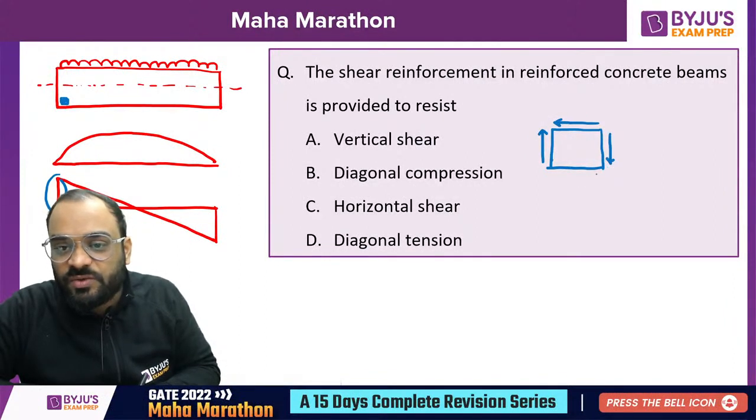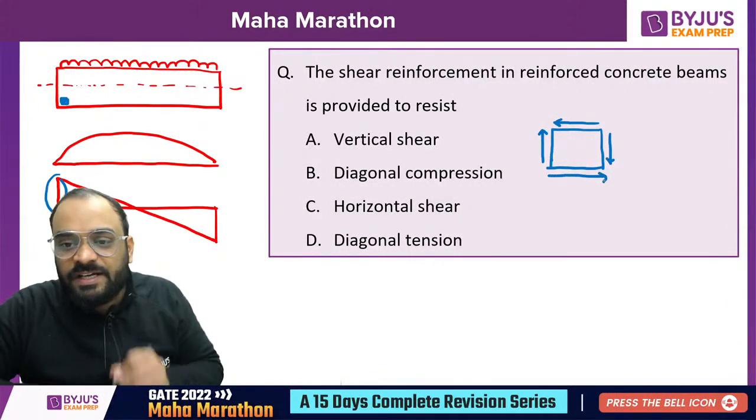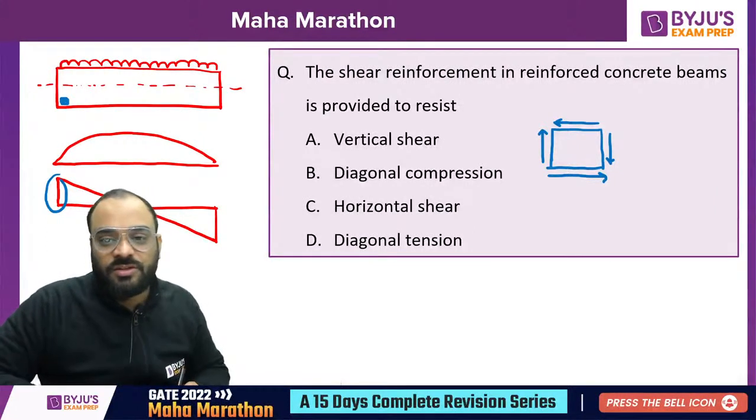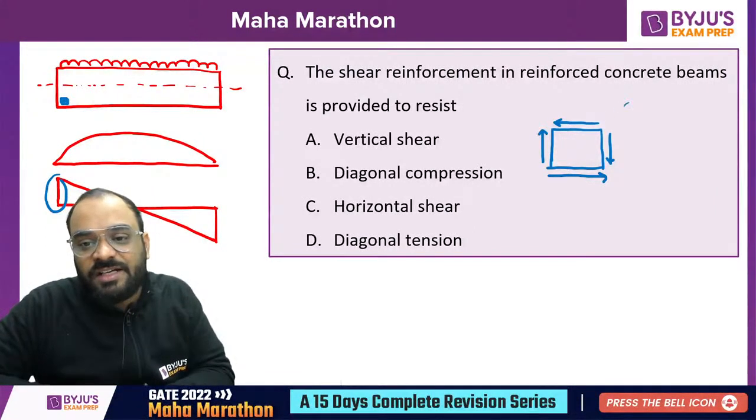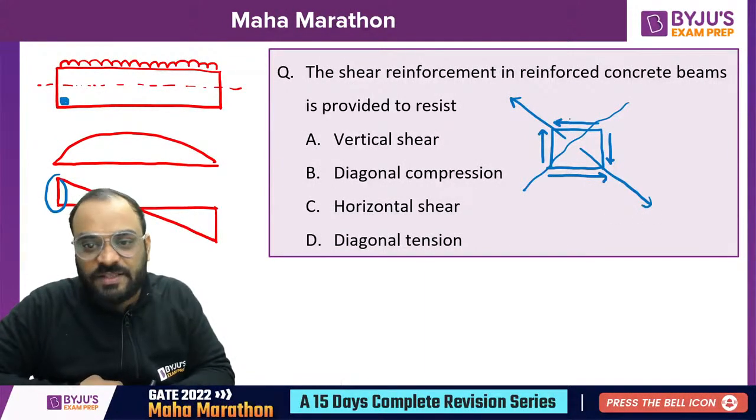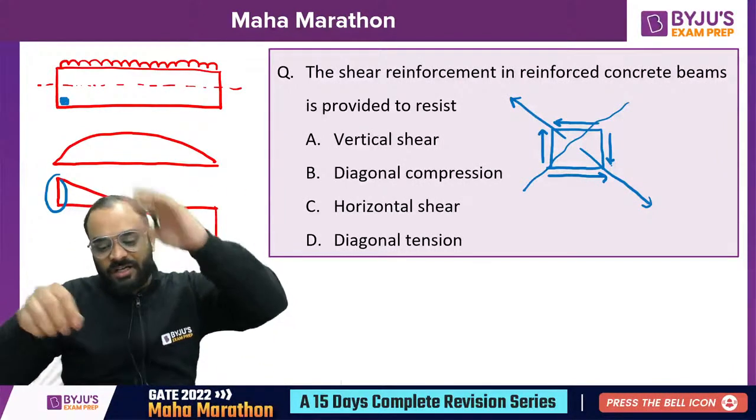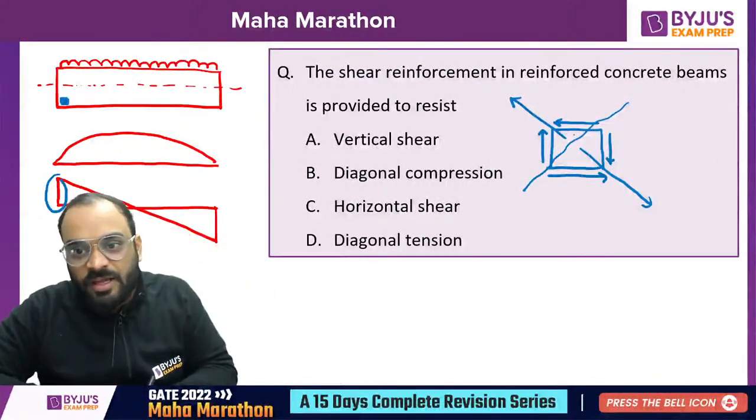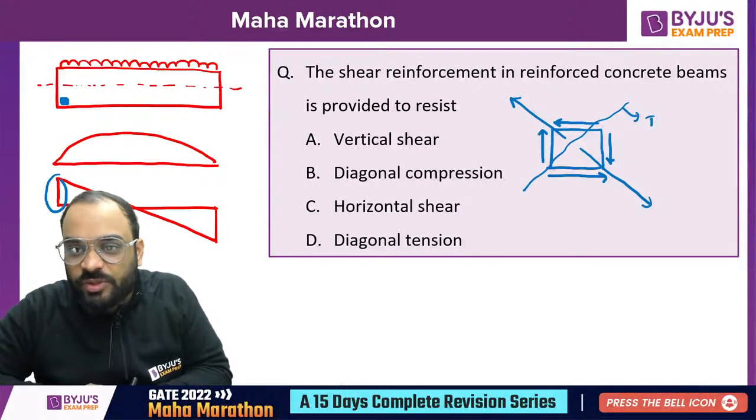This is our shear stress which is present at this particular location. So what will happen? If you find the resultant of it, what you will observe, guys, is that this particular value will become like this and this particular value will become like this. Means we will ultimately get the forces like this. So what happened? A diagonal crack is developing. This one is what? Diagonal crack.